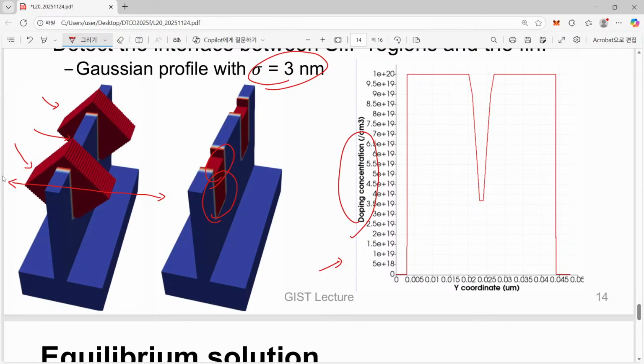So now you can see that there is a certain dip in here. This is corresponding to 7 nanometer. Please note that initially the fin was p-type doped. After that, we introduce a phosphorus-containing silicon part to make this doping profile.